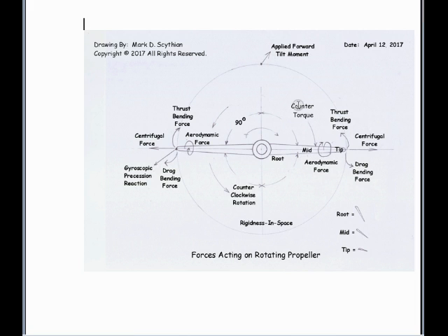But this torque is inherent, but it's also more dominant during the RPM changes, because then acceleration is changed in the RPM on a rotational plane. And so there's a little bit of a counter torque moment that takes place. And this is applicable to anything that rotates, whether it's a flywheel on a car or any type of rotating structure. The mounts have to have a torque arm to cancel some of that torque out and absorb it on a flexible torque arm, so the mounts don't fall apart from constant torque stresses.